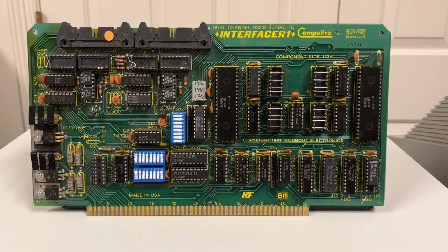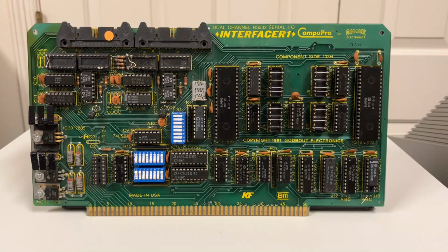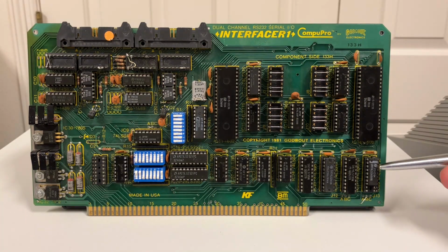What these chips were was like an upgrade path from the very popular 6 element buffers, the 74367 and 368. It has the exact same pinout for the first 3 buffers on this side and the last 3 buffers on that side as the 74LS367 or 8. Now those are very common chips. I happen to have a 368, which is the inverting one, in stock in my office, and all we really need is 6 of those buffers in order to fill the status register with the bits we actually need to drive. So I actually put a 368 in here.